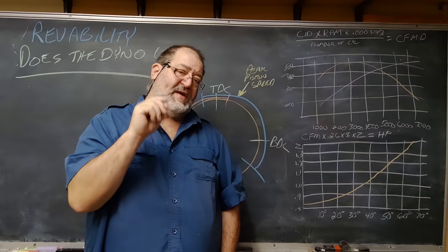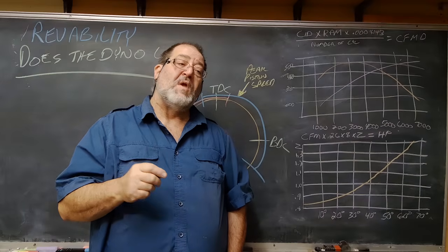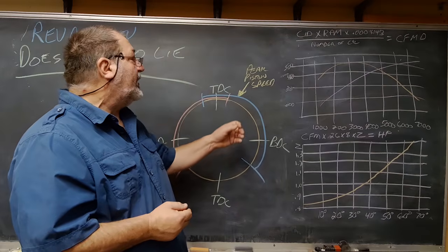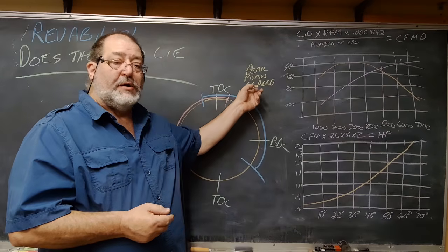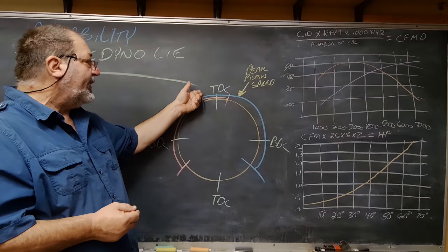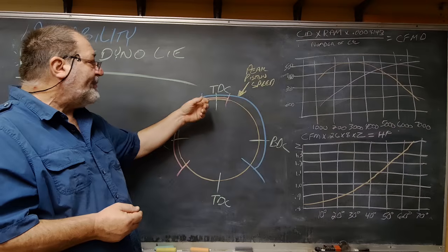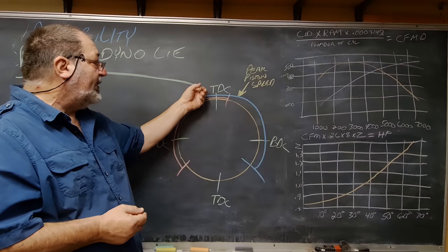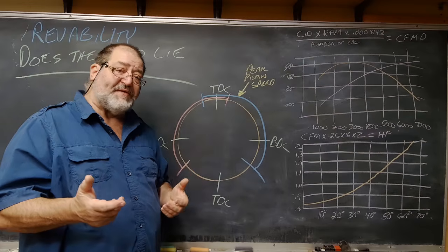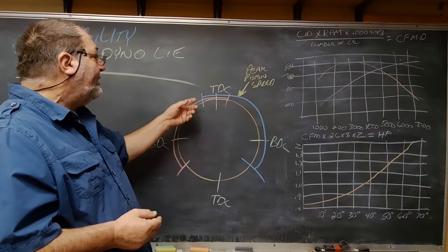I need this much flow. Well, in my experience, you almost can't get there. You're always trying to open the valve earlier. And I'm always trying to open the valve earlier and limit my overlap, which is a difficult thing,